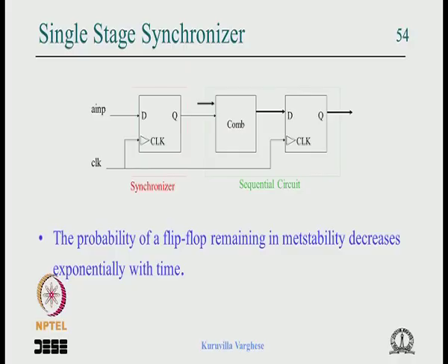you got the picture. So the idea is that we give enough time for the synchronizing flip flop to come out of the metastability, from which point onwards we can analyze that part. The time available for it to come out of metastability is that in this part there is one clock period; a clock comes and before the next clock edge this output should reach here.